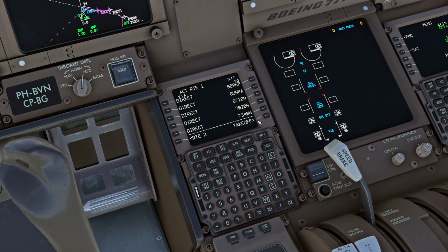There are different ways of entering coordinates in the flight system. So I'm just gonna show you on the legs page. So for example, let's take a random point, 72 north, and then west. Let's take a look. 060 would be entered like this, for example. You can look up in the documentation other ways of entering such coordinates, but just to show you how to enter a coordinate like this, or you just type it out fully like this. So we're just going to erase that for now.